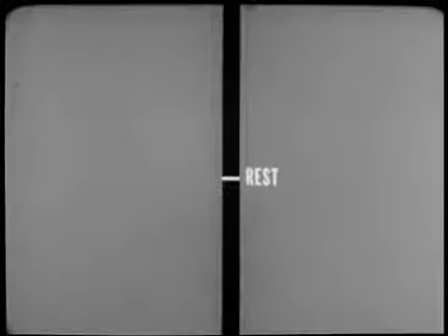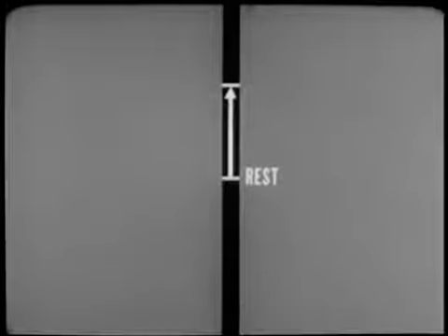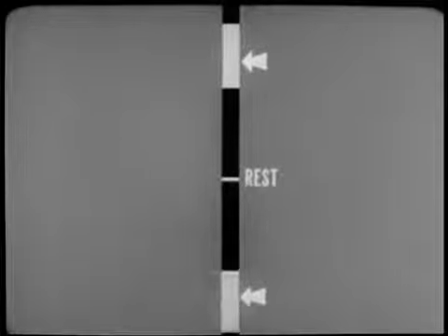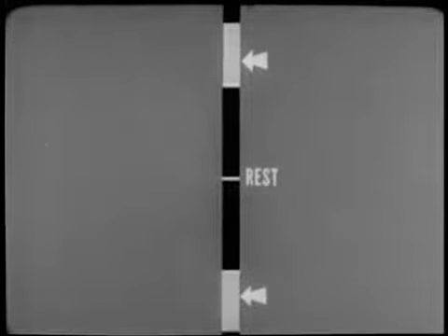This is called the carrier's rest frequency. The bandwidth will include an equal amount of frequencies above and below rest frequency. In addition to including a range of frequencies above and below rest, the channel will also include two guard bands on either end for channel separation.